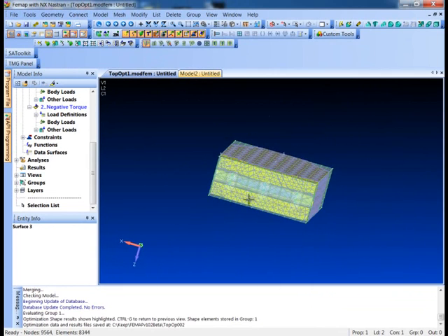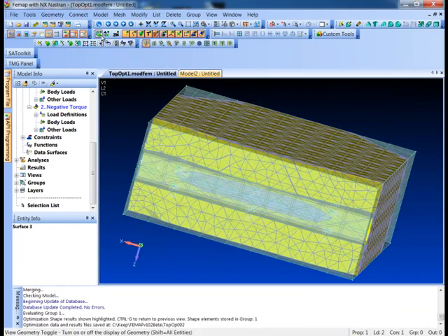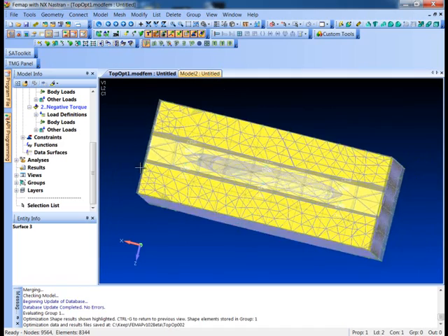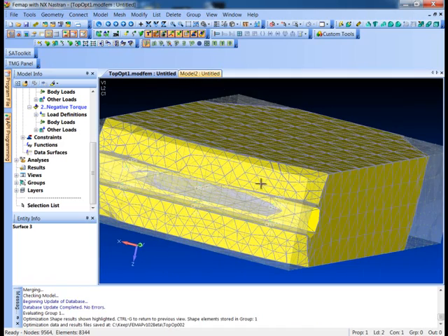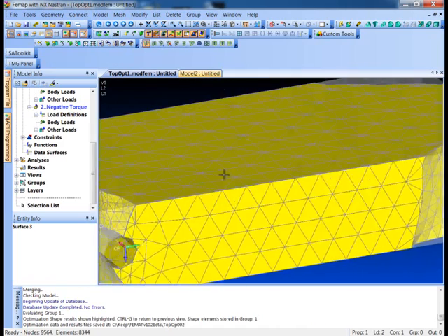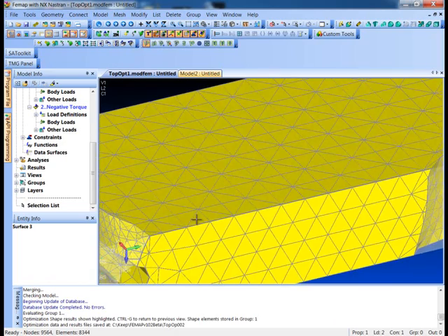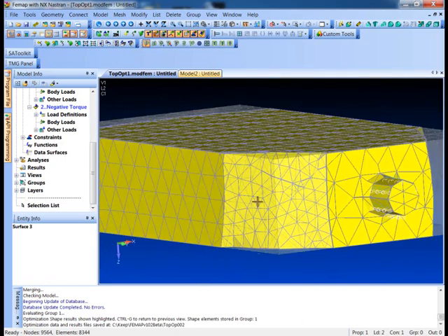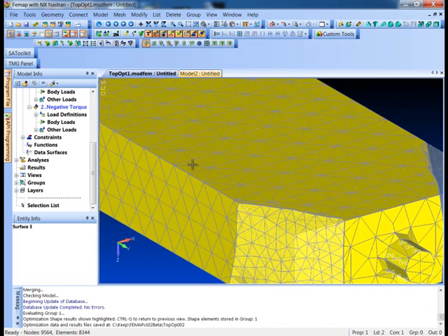And if you look up the inside here, let me turn off all the geometry so we just have the mesh here. You notice it actually started carving in up the middle. So it's actually suggesting to me that the design modifications should be to basically hollow this piece out, take off some of the edges here, and leave the rest of the part.